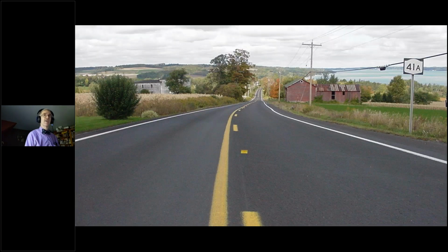Obviously, there's a roadway that's fairly new in terms of having maintenance on it. It just had a slurry seal the year before the photograph was taken. You're obviously not going to do anything on this particular roadway for a while. But part of your asset management is to make sure you look at every single roadway and figure out when you do need to do the maintenance. We do maintenance or preservation way too late most of the time. Do it sooner than you have to, but doing nothing is part of the game. So knowing you don't have to do anything is good.